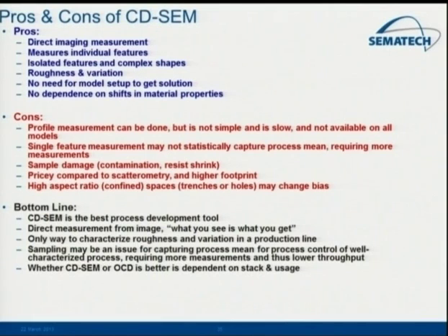So, CD-SEMs, as I mentioned, this is kind of the summary slide. The good thing is you get a direct image of what the feature looks like, within the limitations of the electron beam. You measure individual features, so you drive to an individual transistor and measure that transistor. You get the complex shapes from the two-dimensional nature of the image.